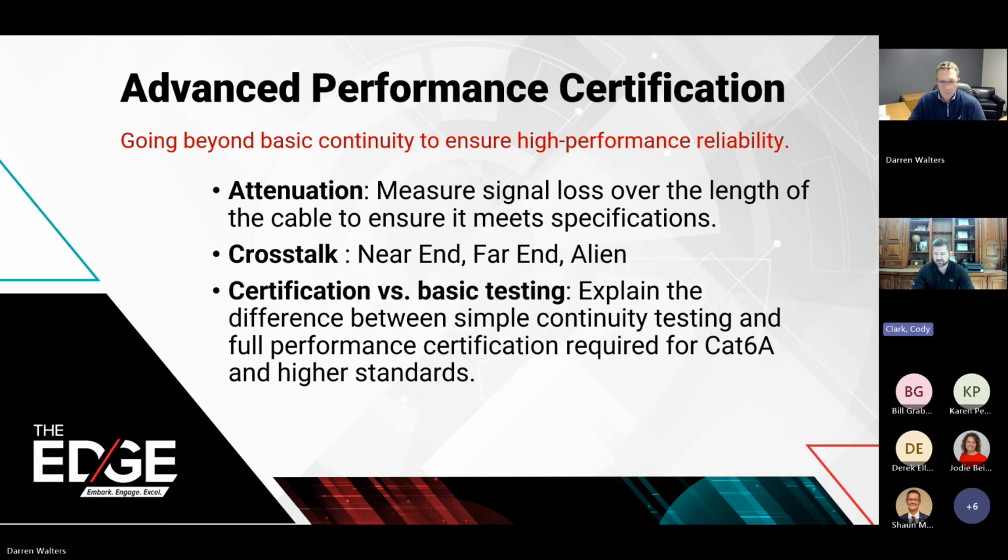And a certification test is required for the warranty, like Darren was just talking about, because that's what's telling you that your system's actually going to perform the way it was supposed to, not just that it was installed and the connections were made properly. So some of those things that they test are attenuation, which is your signal loss over the length of that cable, or crosstalk, both near and far end and alien. So are the pairs within that cable crossing over and causing too much interference with each other that it's going to cause packet loss and issues with your data?